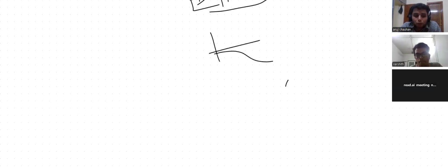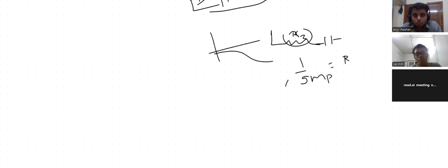Okay. So what did you do to overcome this problem in your design? We add an RZ. Okay, so what will it do? We'll choose the RZ value such that 1 by gmP equals RZ, so that the effect of the zero won't be there, sir. Why are you not using RZ greater than 1 upon gmP so that this zero can be shifted to the left? Yes, sir, we can use that also. Will you choose RZ less than 1 upon gmP or RZ greater than 1 upon gmP? What will you choose?